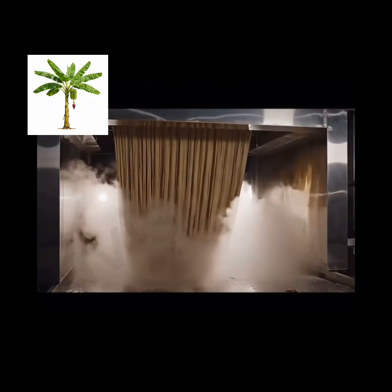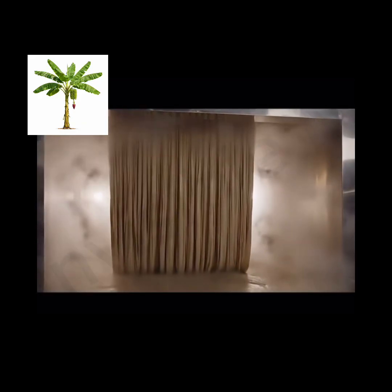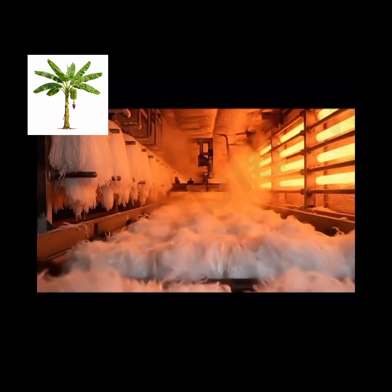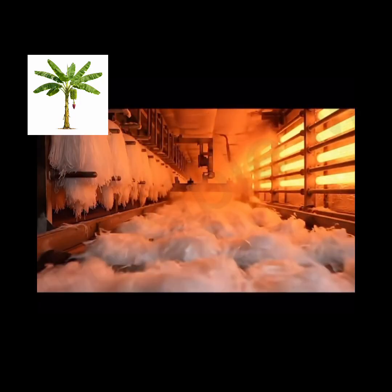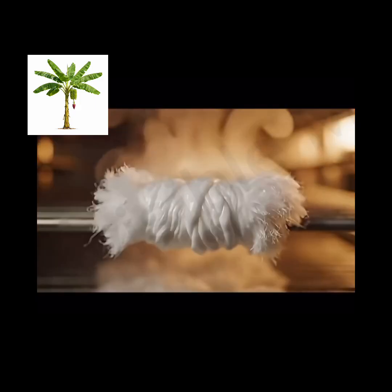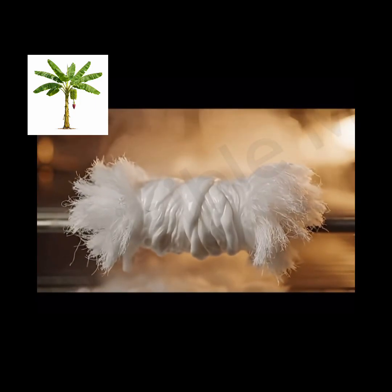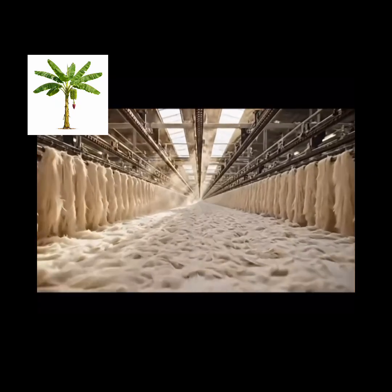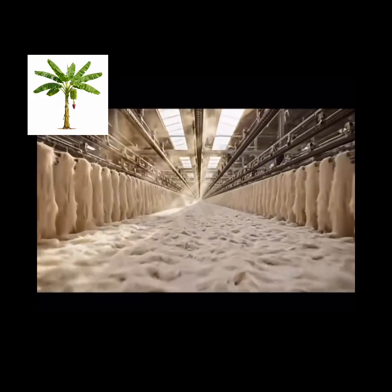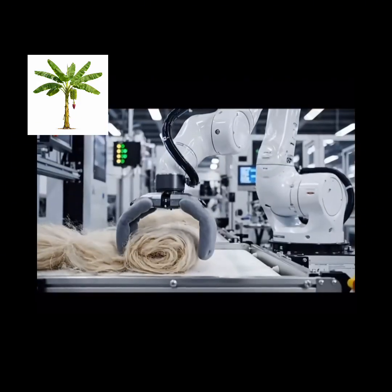Banana fibers are naturally long, or depending on the intended use, they may be cut into staple lengths. Staple fibers can be spun using conventional textile machinery, often blended with other fibers such as cotton or recycled polyester to improve softness and uniformity. The fiber then enters the opening stage. Opening machines separate fiber bundles, remove tangles, and prepare materials for alignment.